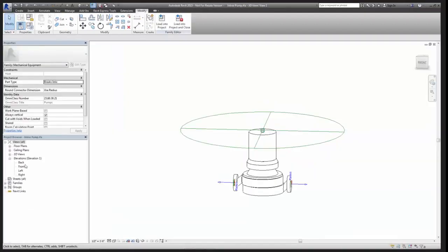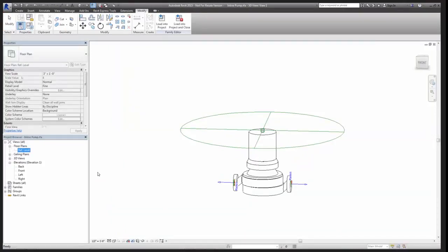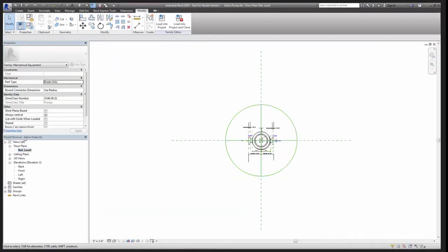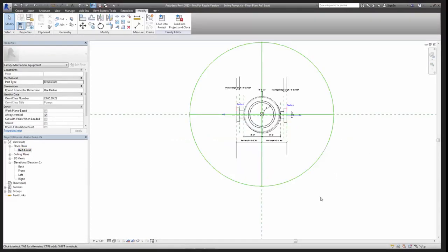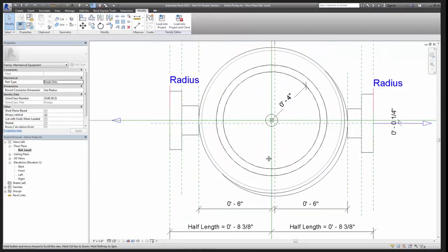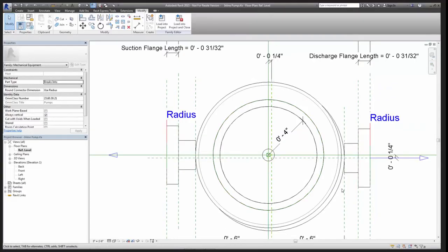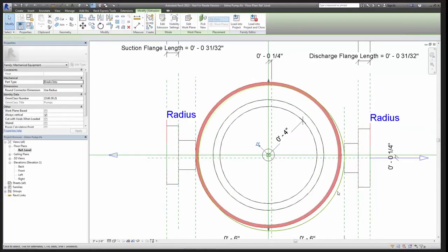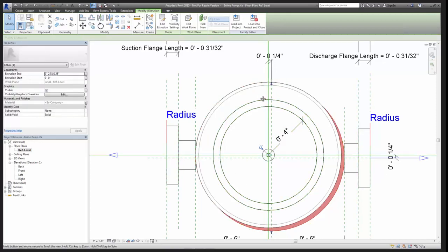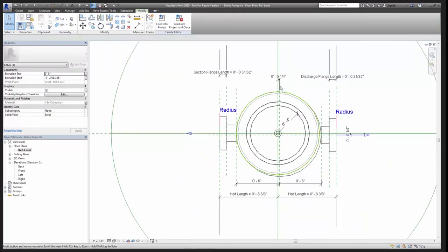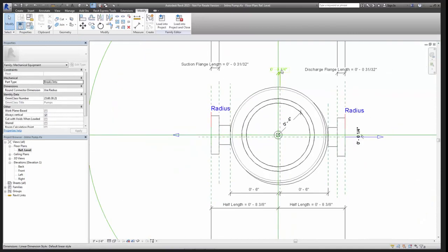So again, in my research in how to fix this family, I found it's really pretty simple. If we go to the reference level floor plan and look at this family in plan view in the family editor, we can see that the issue isn't that it's not inserting properly on the pipe. It's just that it's kind of built to look funny. There's these different circular extrusions that just aren't lined up, and we can see that what is causing that is these 1/4 inch dimensional offsets here.